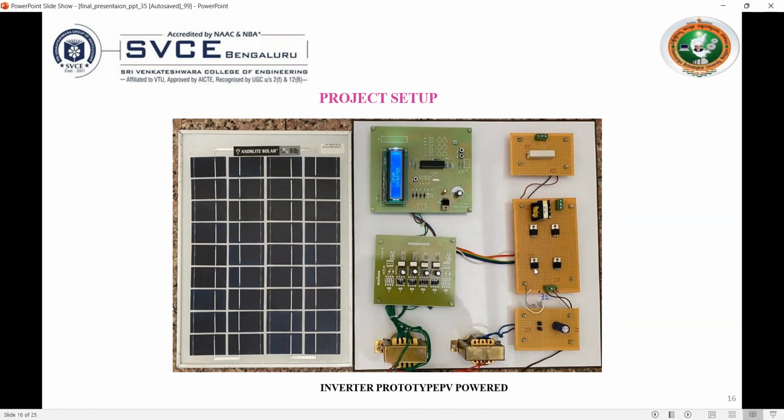The first MOSFET and fourth MOSFET will be working together in one half cycle, and the second MOSFET and third MOSFET will be working together in the other half cycle. So all this is programmed in our microcontroller, and this tapping transformer will be connected to our driver circuit as well as the controller circuit.